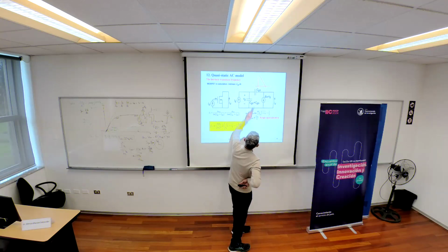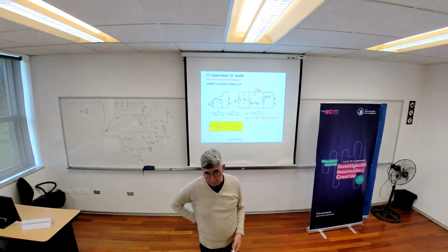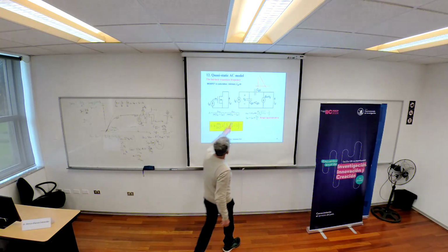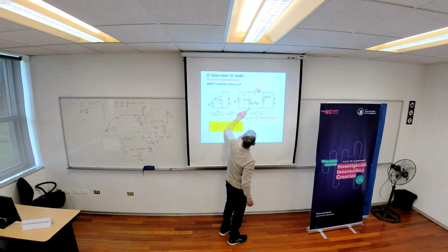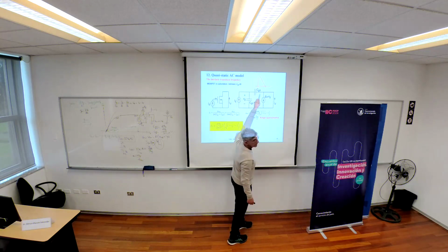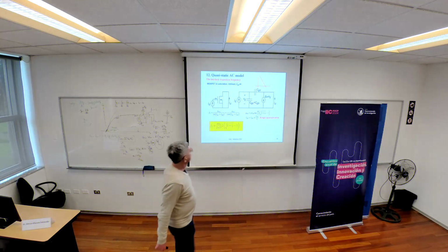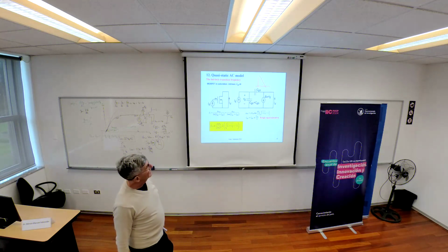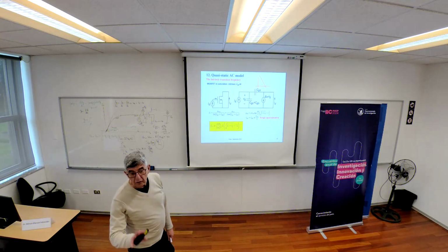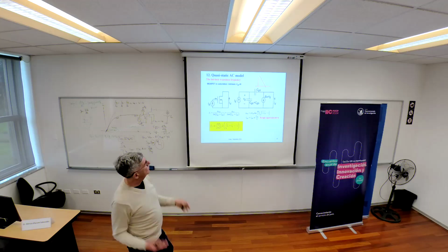You have some way for the current to flow, right? This IG is divided here. Part of it comes to this capacitor, and part comes to this one. Okay. For practical purposes, let's assume that in saturation, this CGD is negligible. This is not true, but the analysis doesn't change too much.